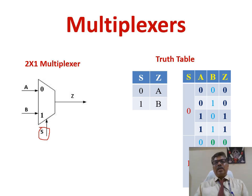If you elaborately write the same truth table, then if S equal to 0, there are 4 possibilities because of 2 variables: 0 0, 0 1, 1 0 and 1 1. Whatever the values of A and B, because S equal to 0, the output Z will take the values of A. Likewise, if S equal to 1, the output Z values are equal to B because B is connected to 1.